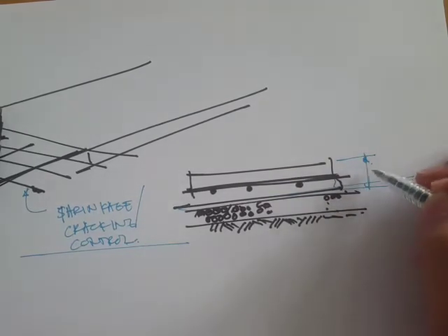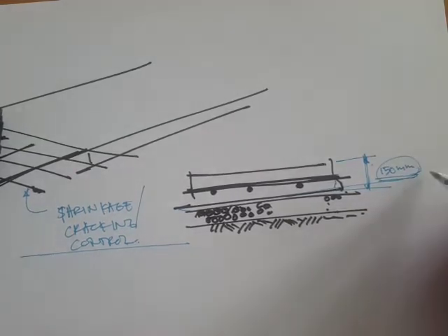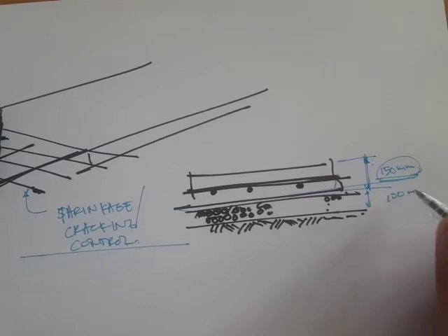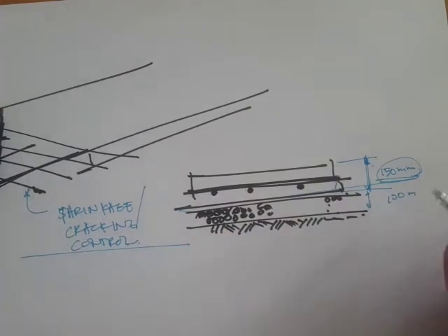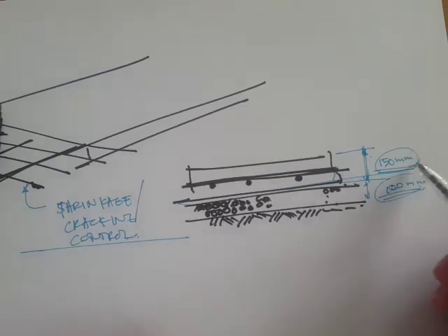So you have to have a thicker slab. The policy specifies a 150 mm thick slab, that's 6 inches, and then a base course of gravel beds of 100 mm, so 4 inches. For some agricultural structures that do not experience that much load as the bag storage warehouse, you can have a smaller thickness, let's say 100 mm.